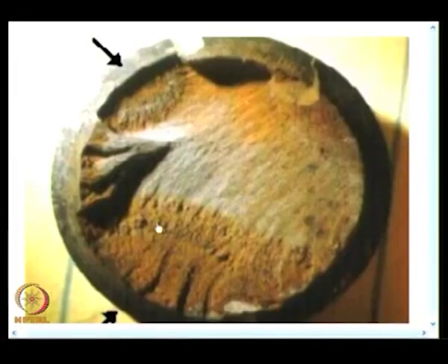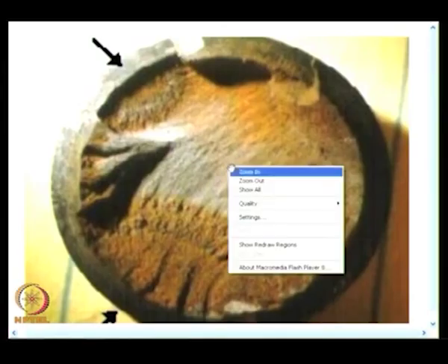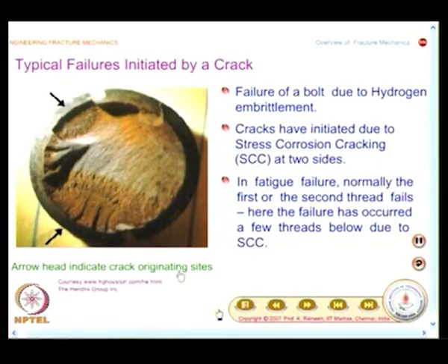Right now you have seen different surfaces. So, this has a different texture and this has a different texture, and you could guess that this is the growth phase of the crack, and this crack has grown bigger than this. So, eventually this would have precipitated the failure of it. This is one aspect of this. You can have multiple cracks on this, one of them may be critical. There is also another aspect that is sought to be explained through this example.